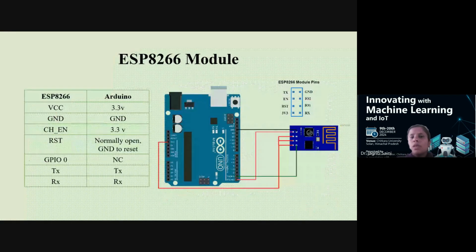Okay, so moving forward, other than this, for the Wi-Fi, we have used this particular module that I have shown you yesterday as well. As I told you yesterday, on this module we have 8 different pins, but not all of them are connected during the hardware connections. Instead, we use some dedicated pins out of that. Note that again, this works on transmit and receive lines. So accordingly, you may have to choose them from your Arduino. Like here we have transmit and receive pins, so we can connect them alternatively over here.